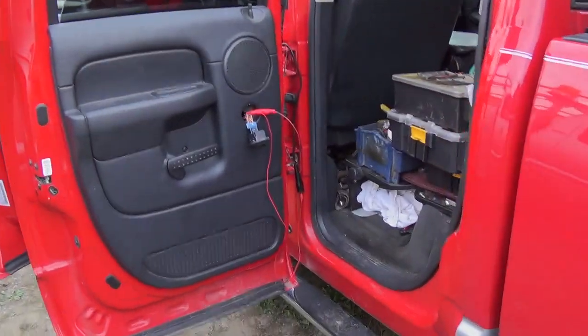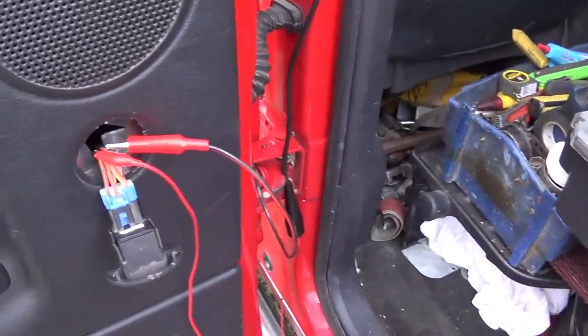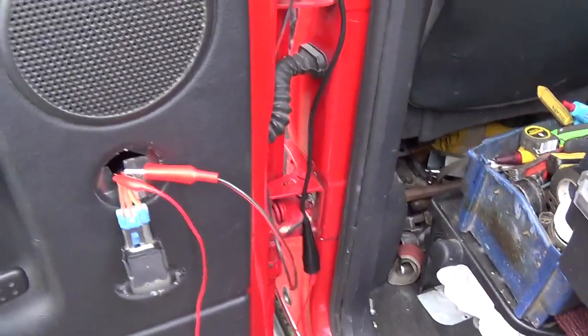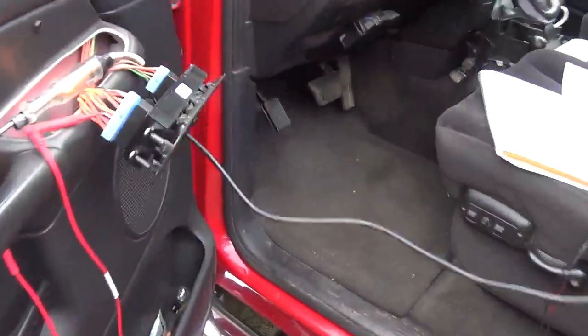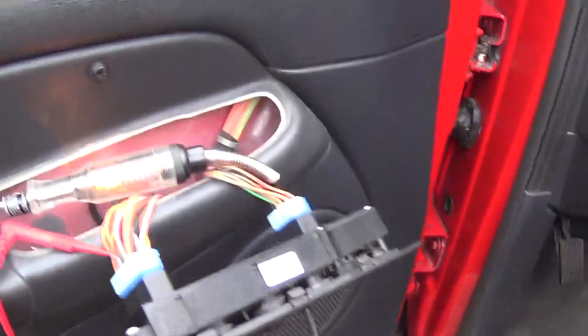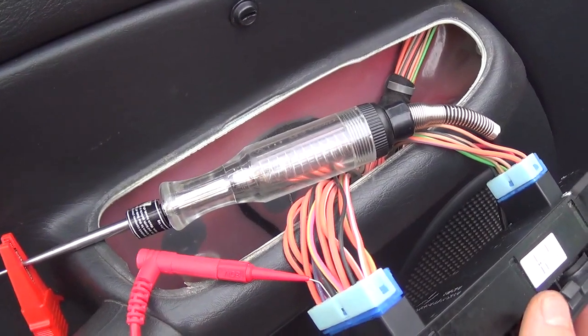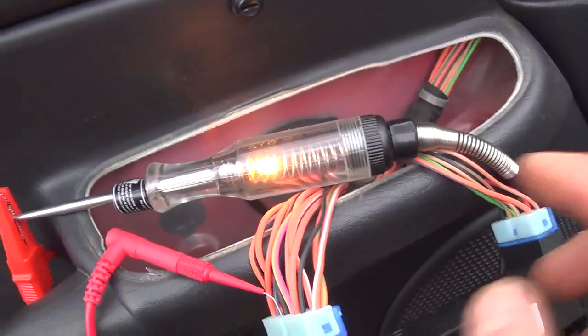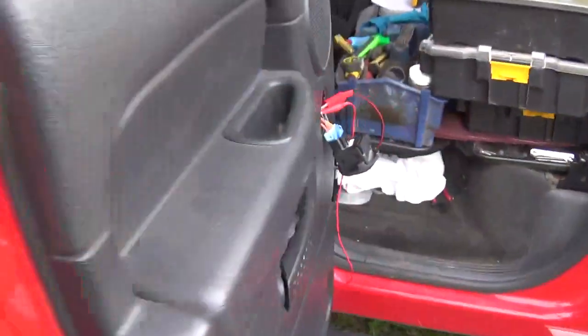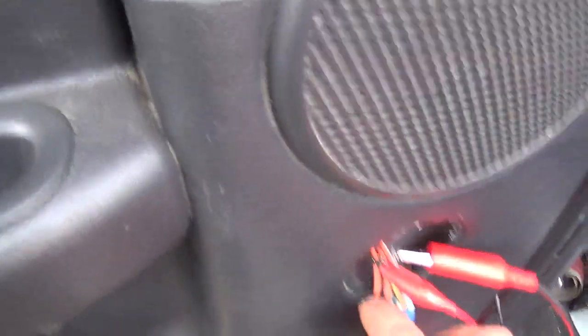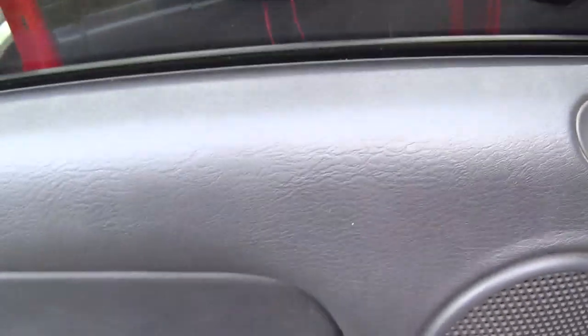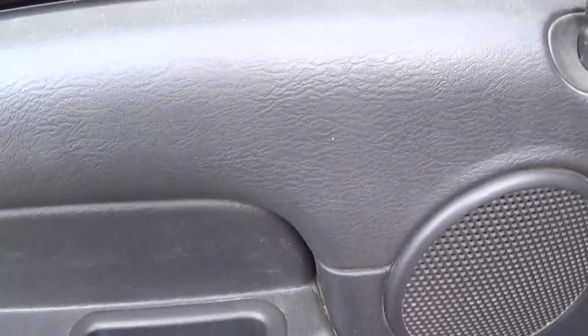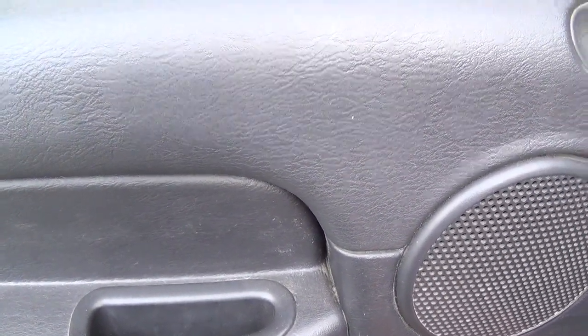Alright guys, I had to step away from the camera here and actually get down and dirty and figure this thing out. So anyways, two issues. First, that broken wire. Second issue is that common feed from the lockout switch. There's a lockout switch, okay? That's depressed, that's unpressed. Now my test light's connected to that same lockout switch wire right here at the window switch. Now see, right now the switch works, everything's great, but just a moment ago it stopped working.